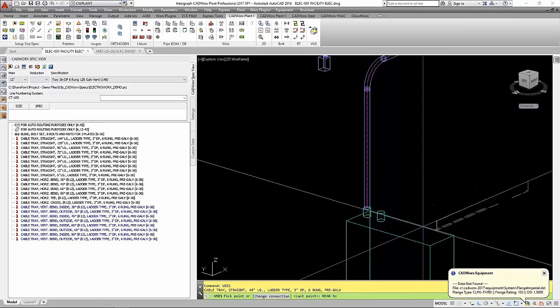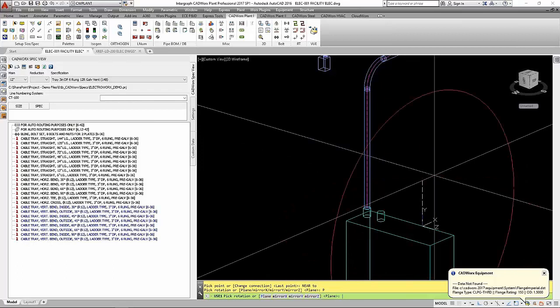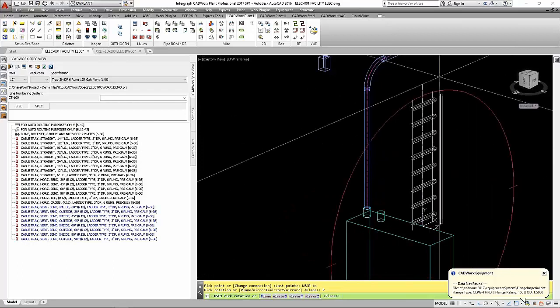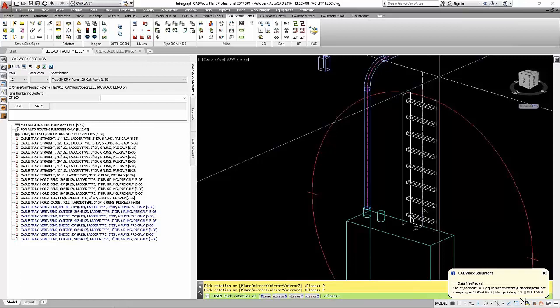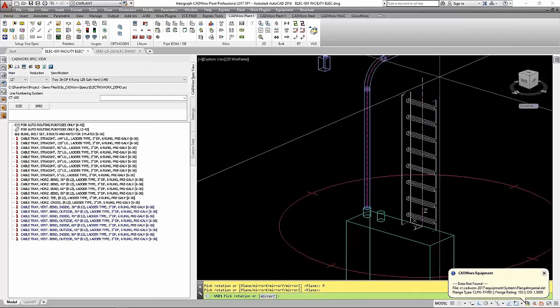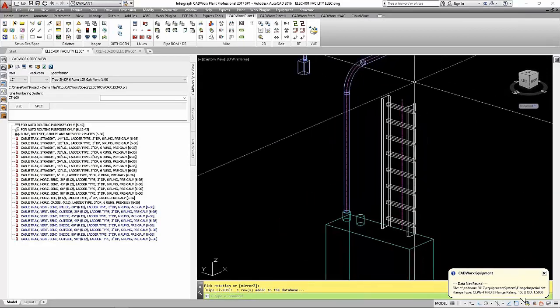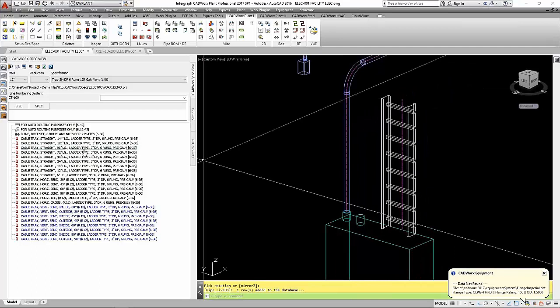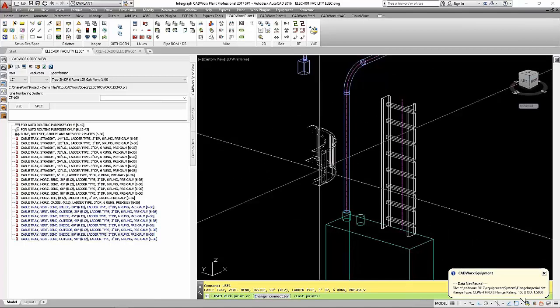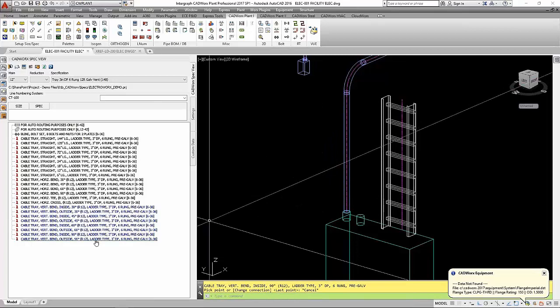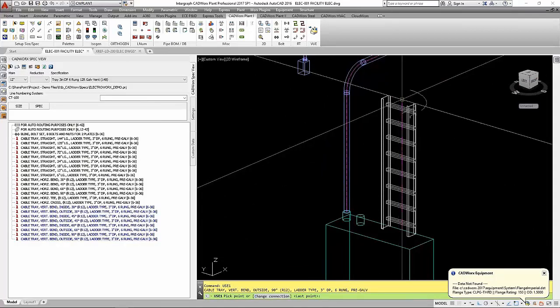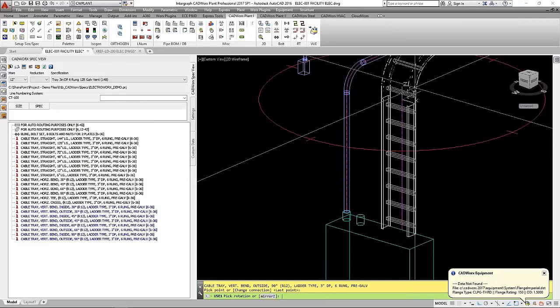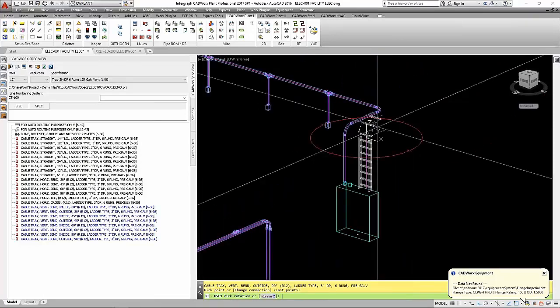Let me drop this in here, and I'm just going to drop the cable tray at nearest, and then I just use my plane to get vertical and adjust my plane just by typing P. Then I can get the orientation exactly the way I want it. And I'm going to put a piece of 48-inch in there. Now let me go get a vertical transition here, and we've got these in here as optional. They're blue. But oops, I picked the wrong one. That was an inside. Let me go to the outside and just pick the last point, and it pretty much just pops right into place and orientated correctly.